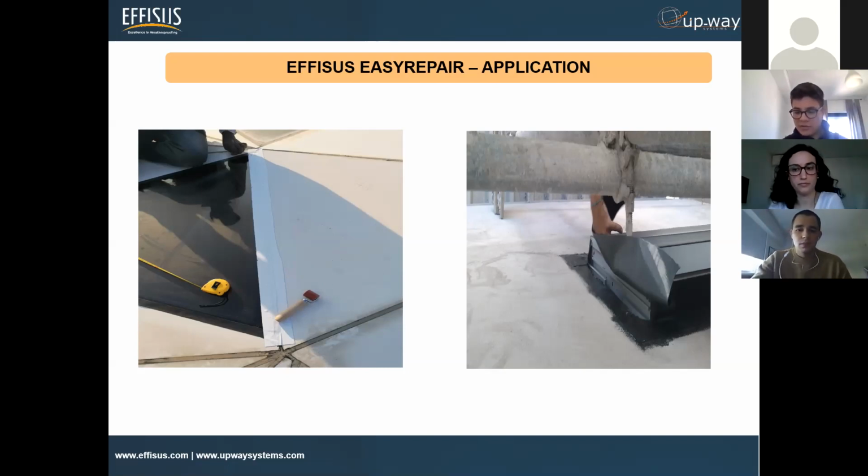John is asking, can I use it on a concrete expansion joint? Yeah, John, again, we need to see how the joints are where we're working. In some cases we do recommend not only applying the membrane, but you can have a backer rod in this expansion joint, and then you apply the membrane on top of it. But yeah, you can use that for sure.